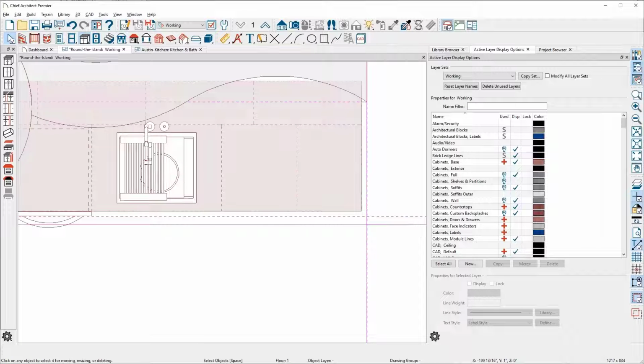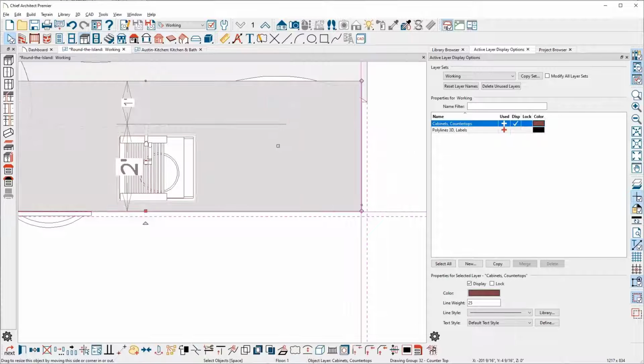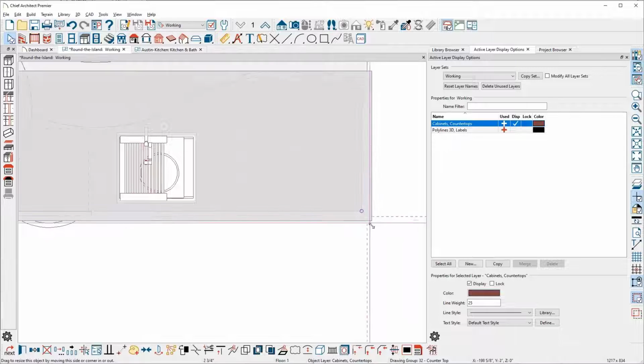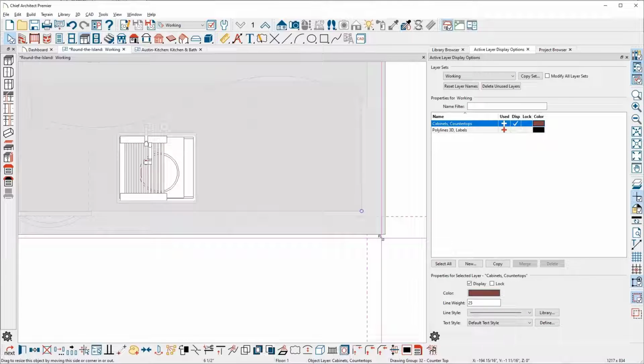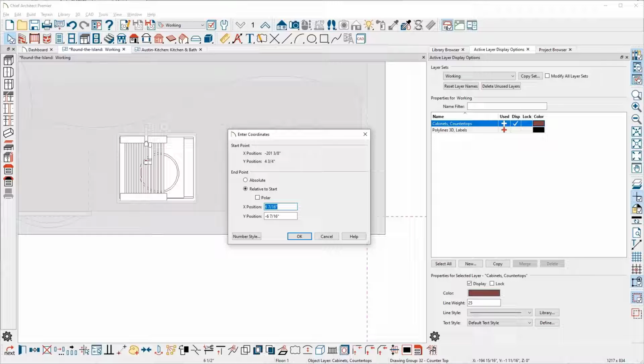And if you want a concentric, symmetric size all the way around, what I did was grab the countertop here and put my cursor over the corner. As I get ready to pull that back, I press the letter C on my keyboard. It stands for concentric. It's a hotkey built in. And then you just pull it out. And if you press the tab key while you're doing it, you got to have extra fingers almost.